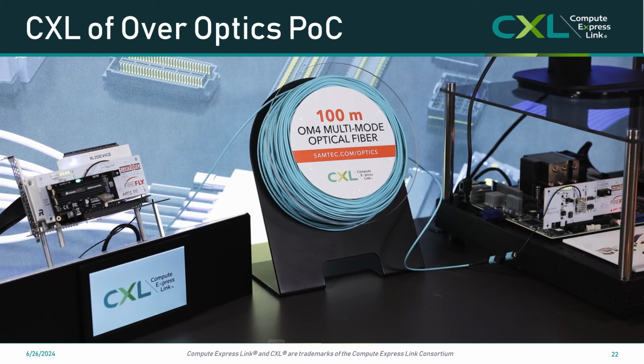And then we accessed, via an endpoint, a CXL device. And while we don't show it on the illustration, we're able to access memory over 100 meters of fiber, using some standard disaggregated memory point-to-point solutions. If theoretically you throw the CXL switch in here, which is one of the next things we want to start working on, that enables memory switching from host to multiple endpoints or from endpoint to multiple hosts as well. So we're really excited about the work that's been ongoing. We're starting to engage customers that are interested in this type of platform, and we're starting to see the advantages of CXL over optics moving forward, moving from proof of concept to reality.